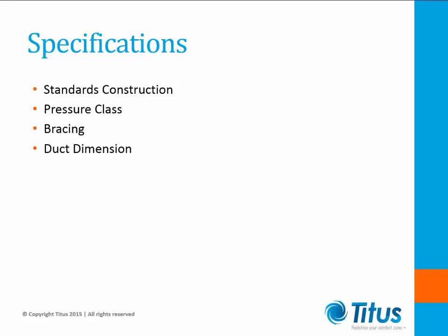If the available space is very limited, the designer can specify a maximum bracing connection height to fit. Be aware that limiting the choices to the bidding contractors can raise the project cost because not all connection or bracing types cost the same.